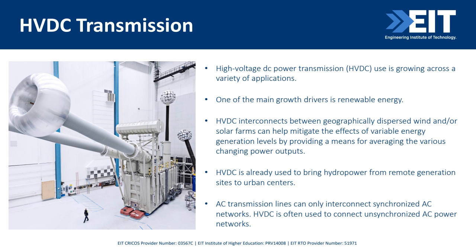As I mentioned, with AC transmission networks, the biggest challenge is the synchronization of different networks, because we need to be mindful about the frequency as well as the voltage, and that can obviously limit our options, or we may need to do a lot of retrofitting, like external components to manage that synchronization.